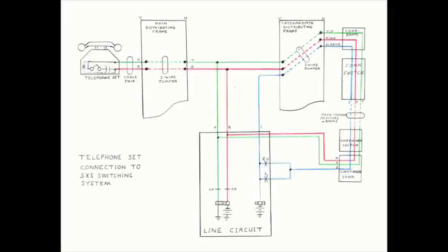Before the E relay is able to release, the connector performs a busy test on the called station to see if the line is idle or is in use on another call. This test is performed by the G relay. One side of the G relay winding is permanently connected to negative 48 volt battery, and at this point in the call progression, the other side of the winding is connected through the sleeve wiper to the called station sleeve lead.